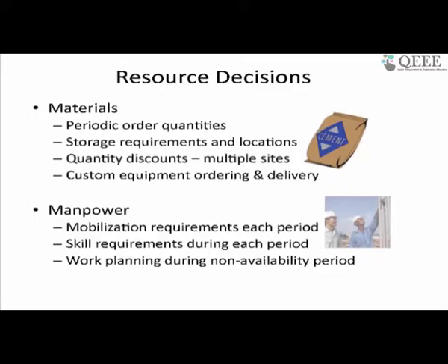I need to know my storage requirement. How much storage space do I need? If material is delivered to a site and there is no place to store, for example, cement, it can get wasted, and that can cause a lot of problems. A lot of times, if a large construction company knows their resource requirements in a region, not just a project, they can order resources for several projects and quantity discounts can be made. This saves the company a lot of money. So accurate resource forecasting on a project becomes very, very important.